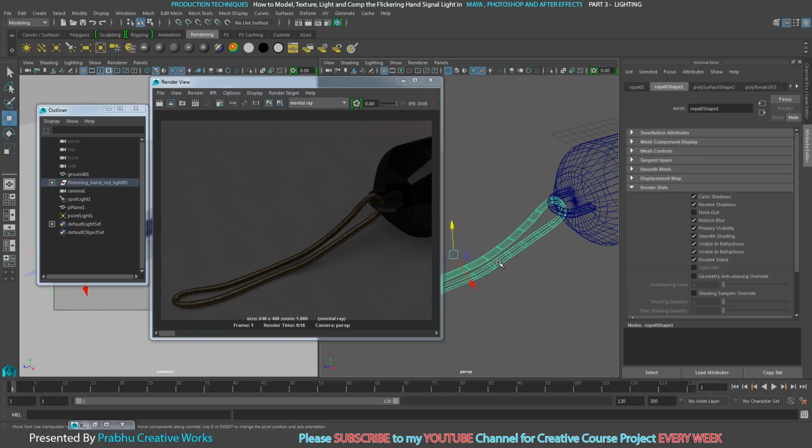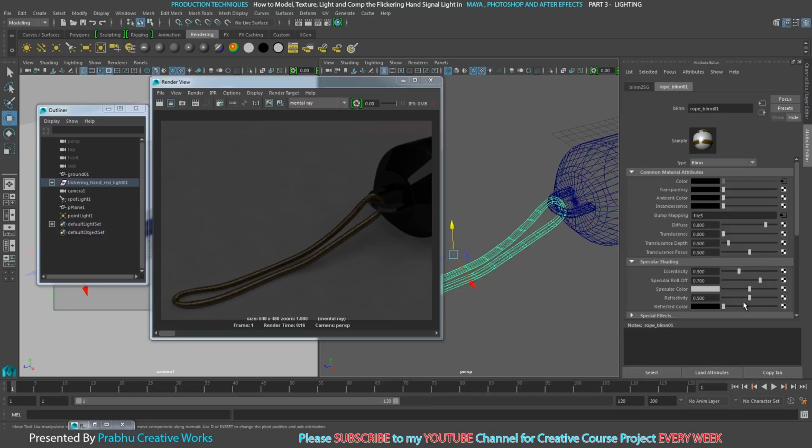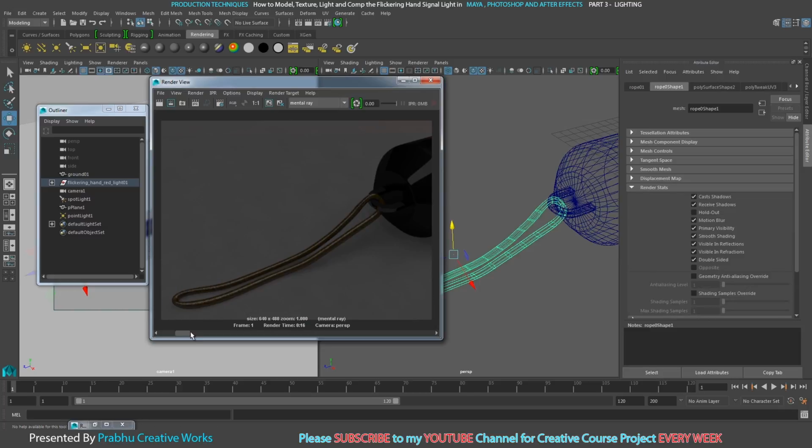So I will select this rope, right click and choose material attributes, and reduce the reflectivity and specular color very low. So I will keep this image and click the render button again. Now we got a very cool rope over here.